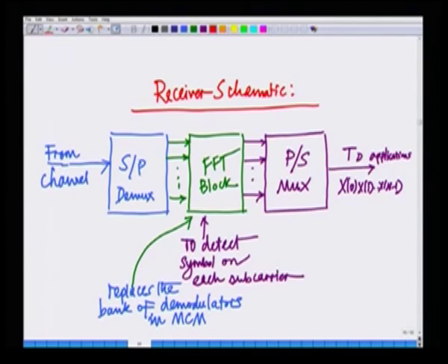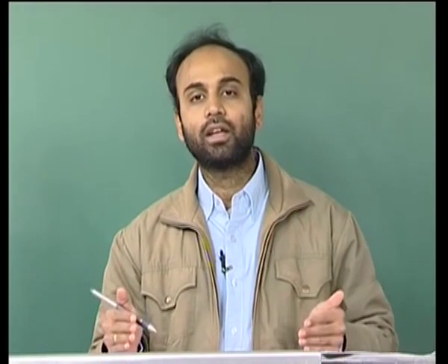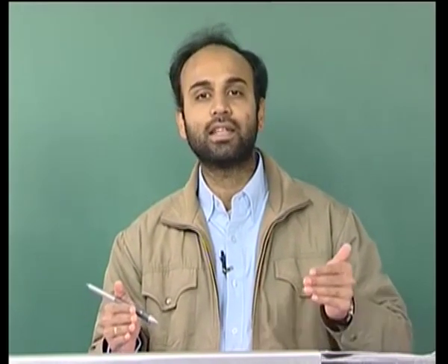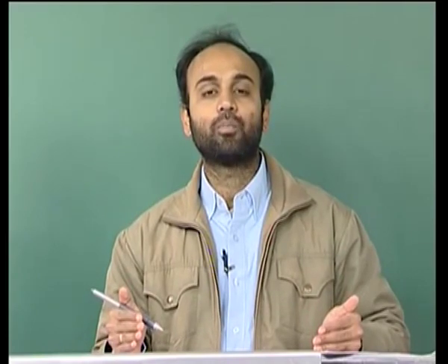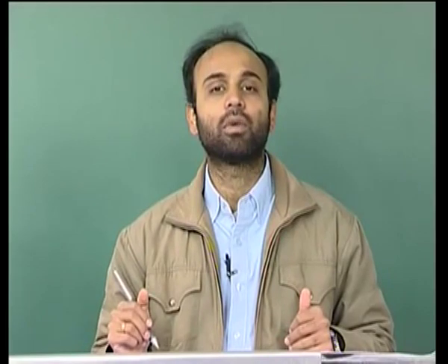Okay. So, what is the novel technique that has been proposed in the context of multi-carrier modulation? The novel technique is essentially to replace the generation using a bank of modulators by an IFFT, which greatly enhances the practical realizability of that system. In fact, it drastically enhances the practical realizability, because implementing an IFFT is much simpler than implementing a bank of modulators corresponding to each sub carrier. That is the great idea which has helped make OFDM possible.